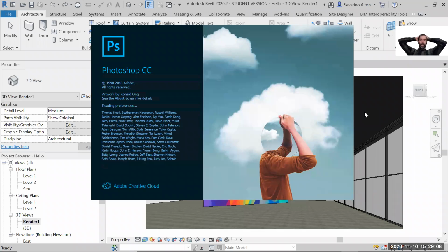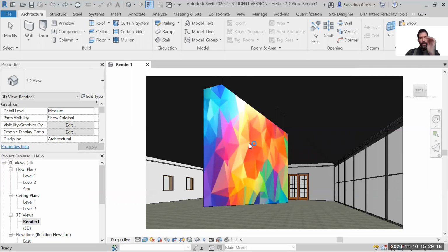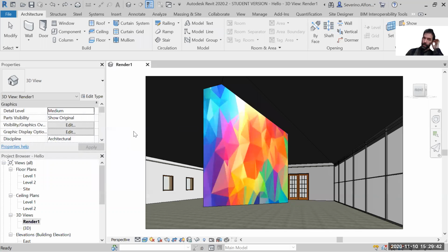Okay, your own material, a bit more tips to do that in Revit. We talked about this again last class. The most important thing is always to search for where you change the material you want. For floors, it's quite straightforward. It's an issue of layers. For ceilings, it's an issue of layers. For roofs, it's an issue of layers. For walls, it's an issue of layers. So you go to the edit manager, and then you go to the structure and change the materiality of whatever layer. I always recommend, obviously, to duplicate that type.